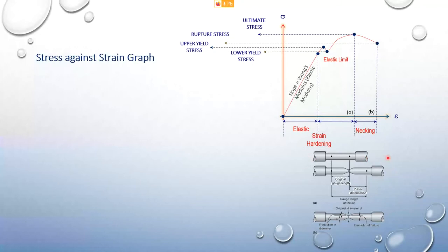this force here, the tensile force, when you remove the tensile force, the material will spring back to its original length, giving you the same distance between these 2 points. Then we say the material is elastic. That means we refer to this point here. But if, for example, this material is further stressed, that means you increase the force, then after this point the material will start to deform partially elastic, or plastic.